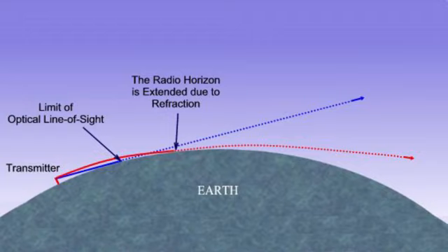Because VHF and UHF radio signals can travel through many non-metallic objects, radio can be picked up through walls or buildings. UHF is better for this due to the shorter wavelength. This is still line-of-sight propagation. Best example of this is a television transmitter. However, ground plane effect is an important factor in line-of-sight propagation, and sometimes moving just a few feet can make a major difference in reception because of what's called multipath.